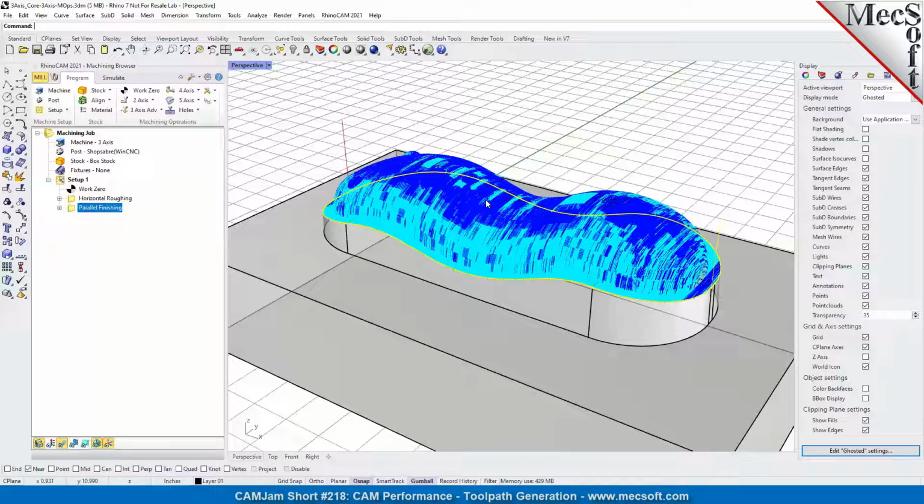In support, we look at a lot of people's screens and see how they work, and a lot of people have a lot of geometry on the screen that's not needed. You probably have it already separated on layers. Turn off those layers that are not affecting what you're working on. That will improve your toolpath generation time. Just keep it clean, keep it simple, and keep it fast.